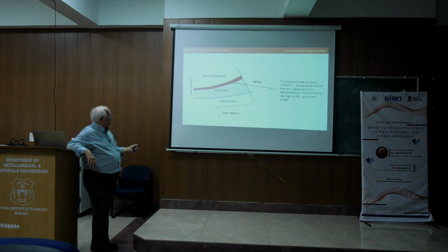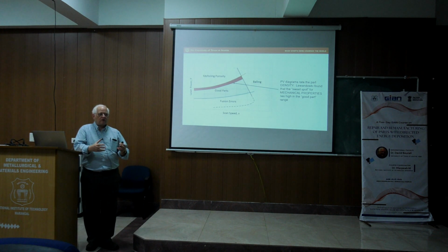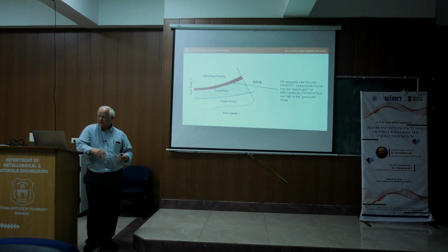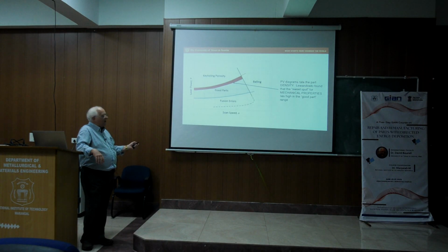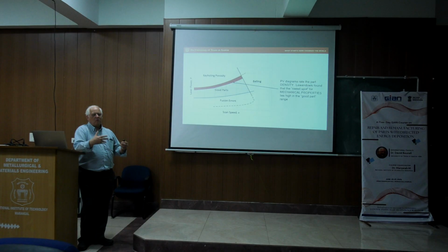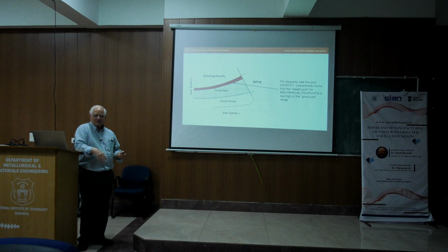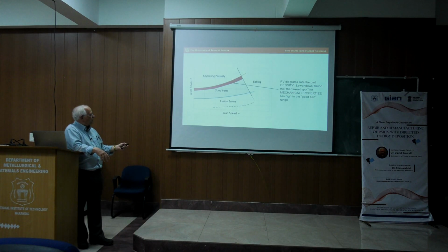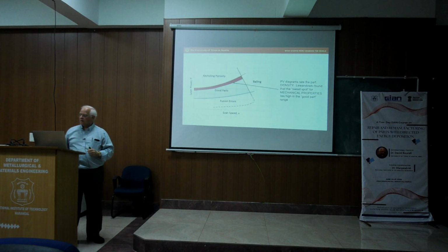So effectively, he determined that if we want parts with good mechanicals, it's not good enough just to be in this region, but rather we want to work up here at the highest power possible. Basically, we want the highest energy density possible that does not cause porosity, which means we want to be way up here. This is where the sweet spot becomes for obtaining parts with good mechanical properties.